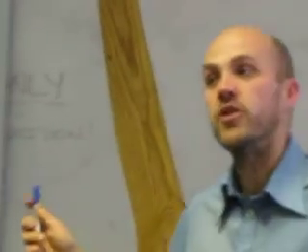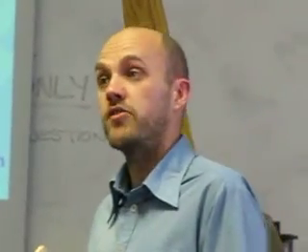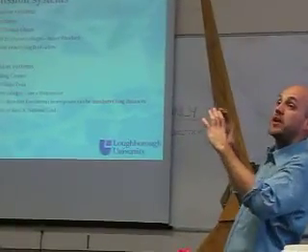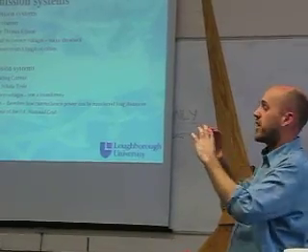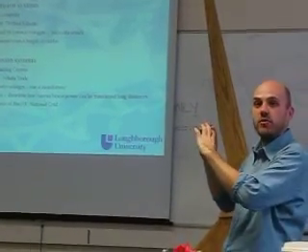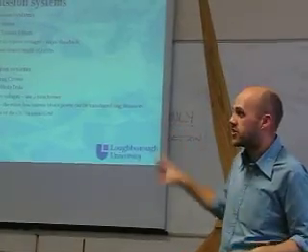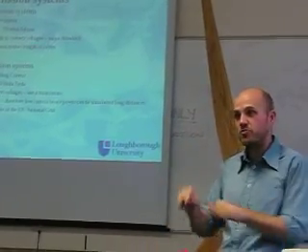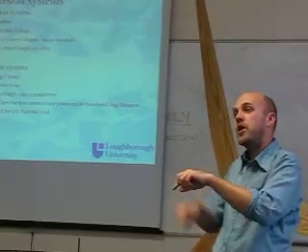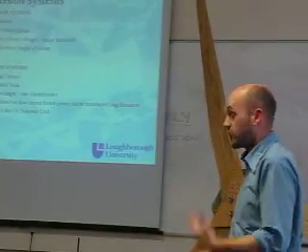So basically what we're saying here is resistive losses restrict the length of these cables. With the voltage that Edison was generating, up to about 400 volts DC, the maximum cable length he could do was about 5 miles. As you get further and further away, to reduce the resistance, you have to make the cable bigger and bigger and bigger. He got to a point where you just couldn't make cables bigger, it wasn't worth it. So he was building loads of little power stations within 5 miles and supplying people. That's what happened originally.